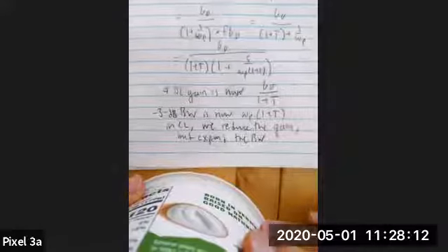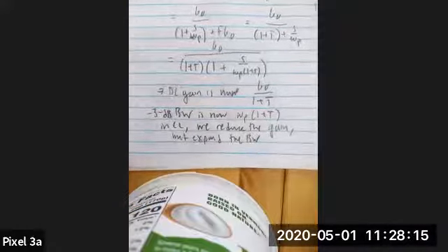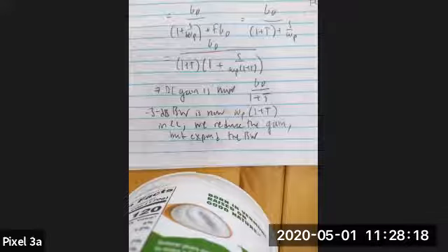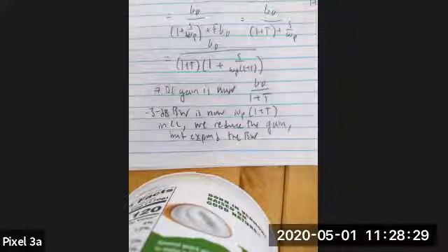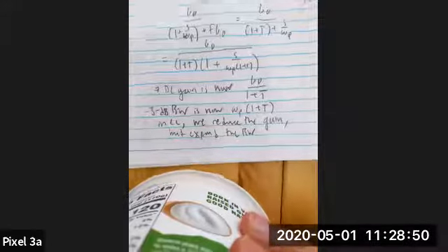And so, this is actually a really useful property, because it turns out when you're making an amplifier, you have to deal with some really, really slow poles. As we saw in class earlier, when you do open circuit time constant analysis, if you have a huge resistance and some insignificant capacitance, that can give you a pretty large pole. And real amplifiers are created with the same techniques that we are beginning to see in class here. So it's kind of expected that in some cases an amplifier will not have such a high omega p